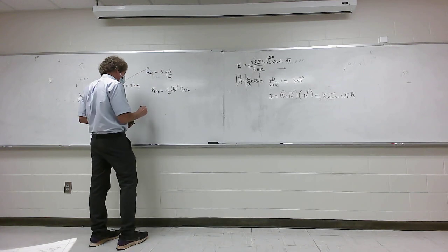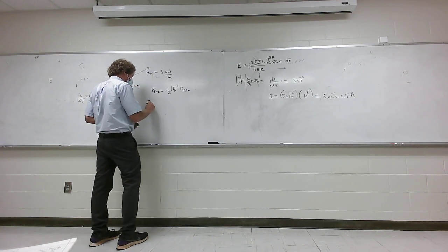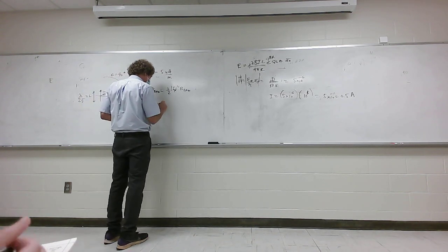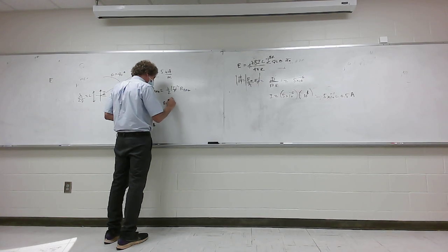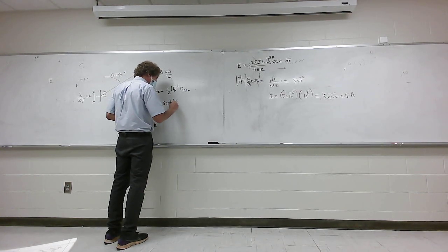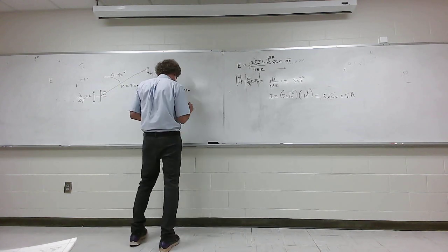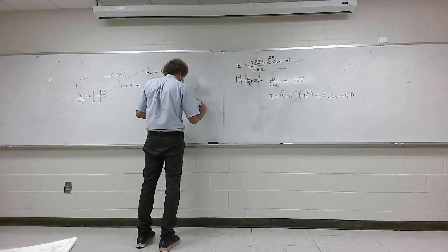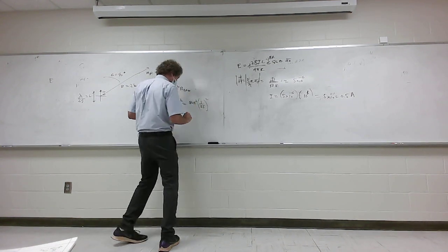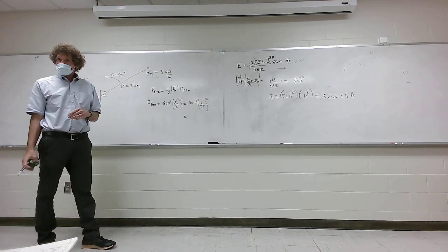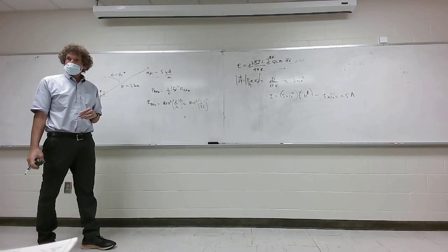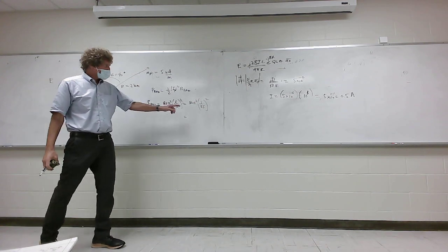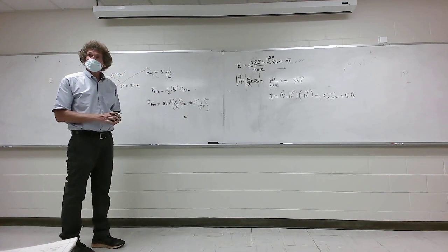R rad for a short dipole is equal to 80 pi squared L over lambda squared, and in our case, it's going to be 80 pi squared times 1 over 25 squared. I don't know what that is, but that's the radiation resistance. Y'all follow me? Once you have this radiation resistance, you plug it in here to get the power.